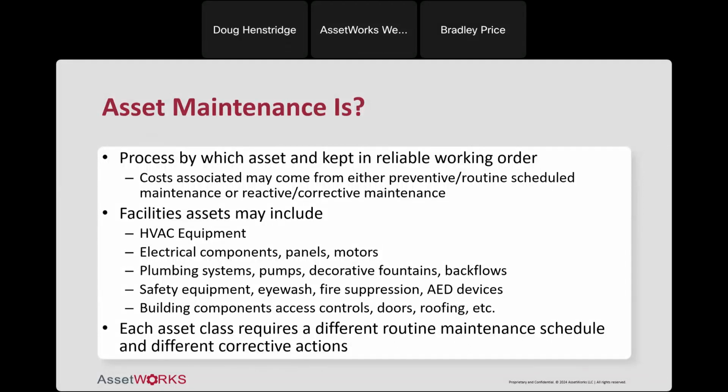Some of the inspections we're talking about are as simple as going through a facility monthly and making sure, for example, that AED devices and fire extinguishers are there and accessible, that emergency exit lighting is actually working, and that emergency doors open and close cleanly. In other cases, you have more rigorous inspections, like eye wash stations. Is the water temperature correct? On some frequency, actually making sure valves work and water flows, etc. These are all very common in a maintenance operation.